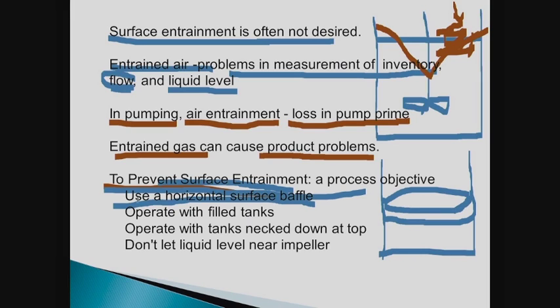Things are new. So I have pictures of significant air entrainment, and I say put a surface baffle on that thing. The surface baffle is going to be a real big pain in the neck, admittedly. But if you have significant air entrainment and it's really causing you problems, a floating surface baffle might be a good choice. I had some of my students run a quick test, and it actually works.